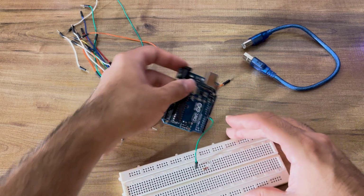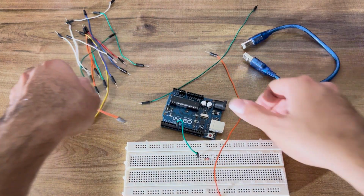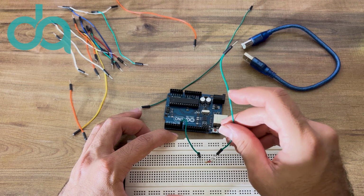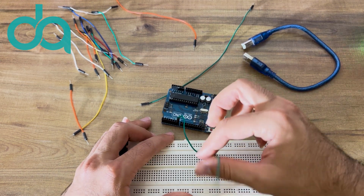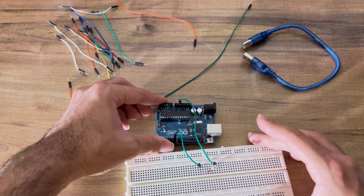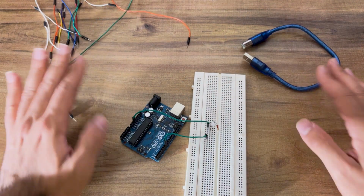Okay, and another pin of LED, I want to connect it to GND. So I connect another pin of LED, or cathode pin, to GND port of Arduino. Okay, and that's it. Very simple and easy.